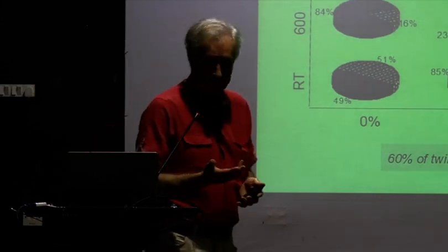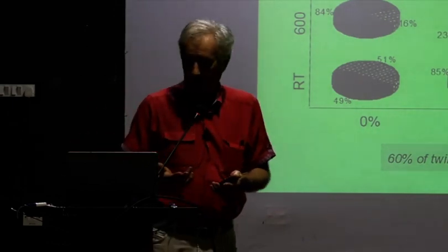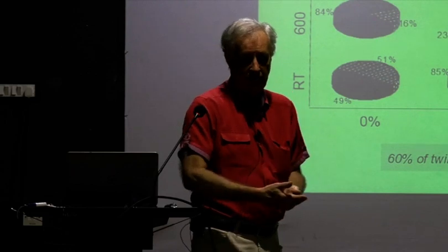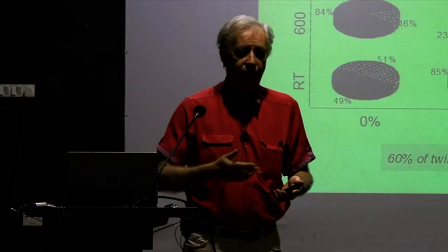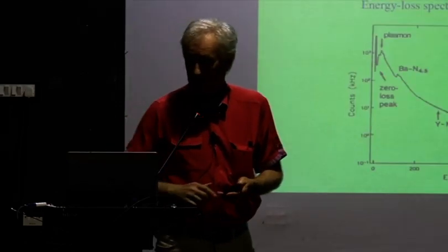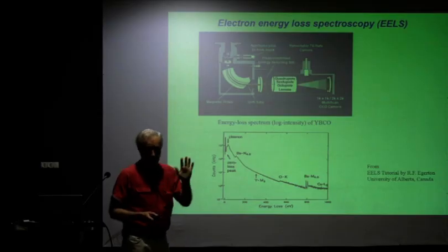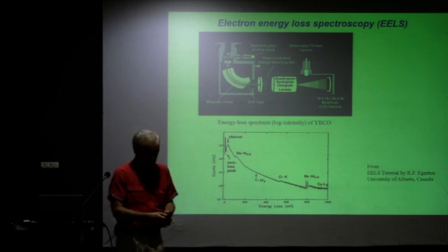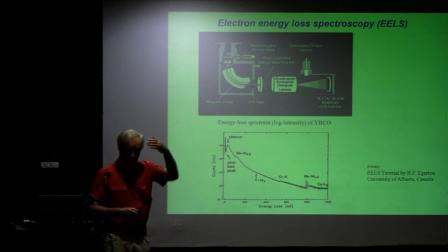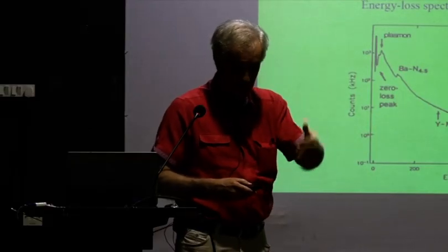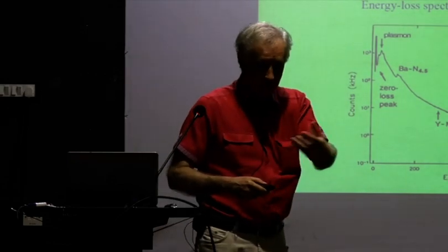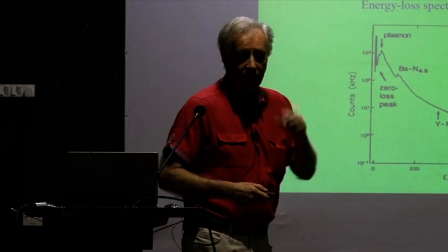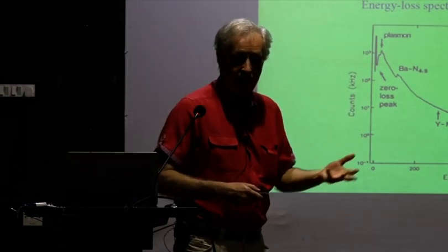So now, how do we know we have these particles? There are several methods, several absorption techniques that can tell us whether there is nitrogen in these things or not. One of the techniques is the one that we use directly with the transmission electron microscope, and that is electron energy loss spectroscopy, so that when your electrons hit your sample, you can analyze it using this particular technique. The energy of the incoming electrons is selected, they come in with something, but when they come out, they can be absorbed by some processes so that you do not have a uniform energy coming out. And if you analyze the energies that are coming out, then you can see where your energy has been absorbed, what has absorbed it.